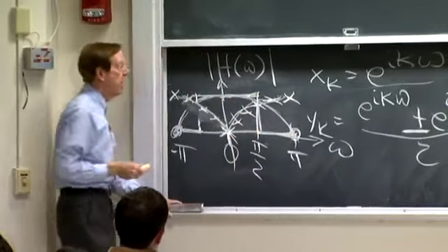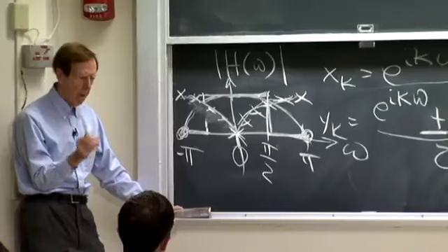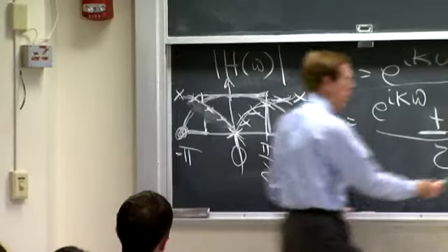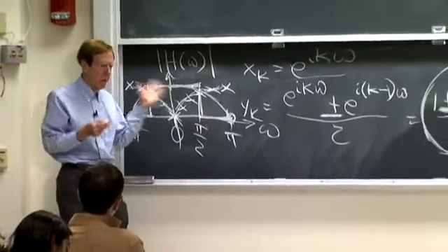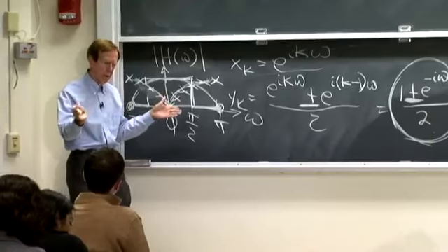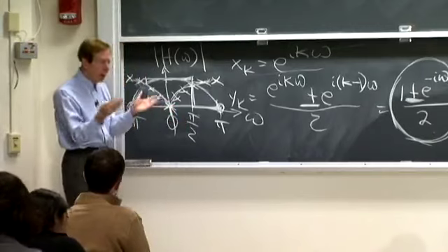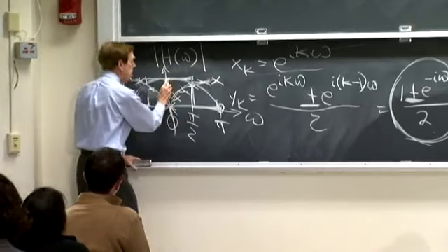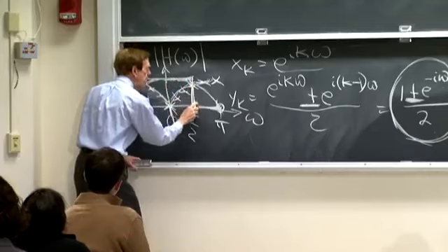So how would we create a closer to ideal filter? Well, we need more H's. With 2 H's, we're doing the best we can with just H0 and H1. With a longer filter, for which we have to pay a little more to use, we could get a filter that stays pretty close to this and drops pretty fast.